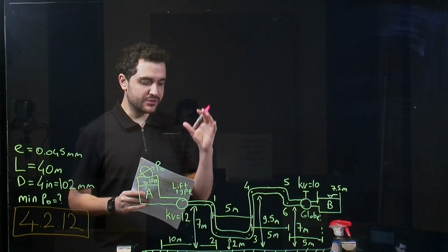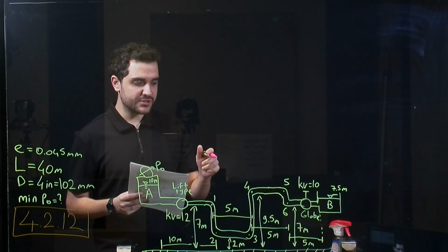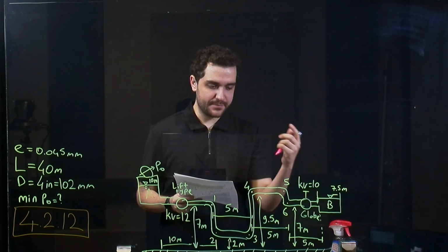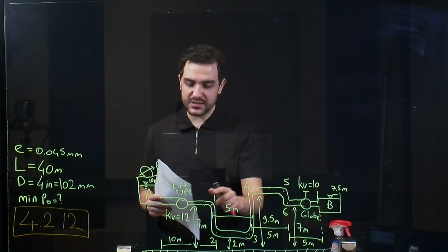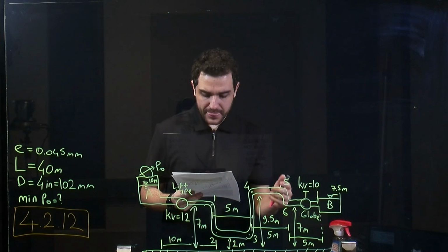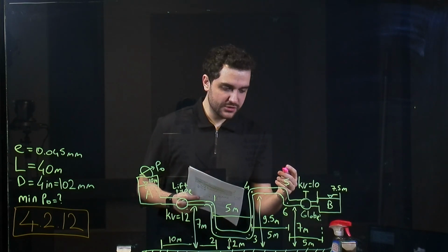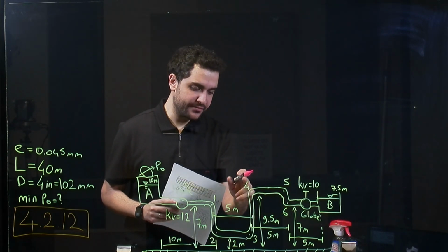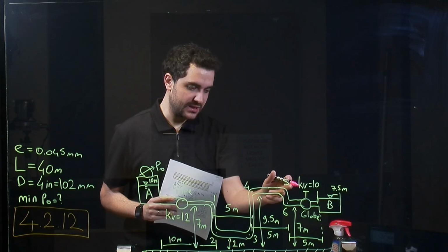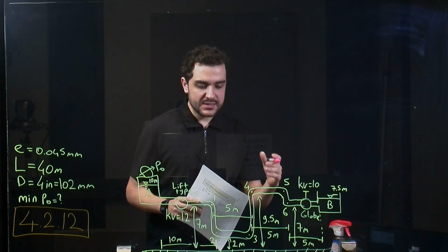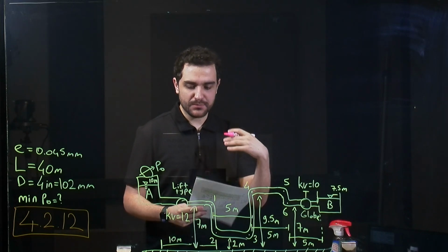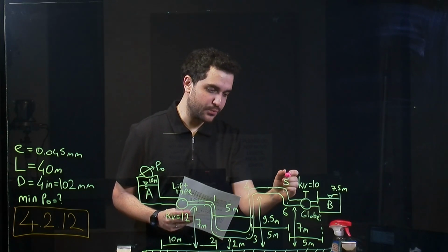So the crucial part here is the most likely location for the negative pressure is the highest point in the system, in the pipeline, so that we can either choose 4 or 5. Since to consider more head losses, we can choose 5.